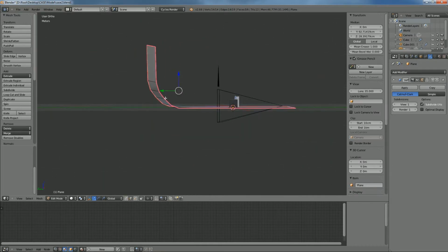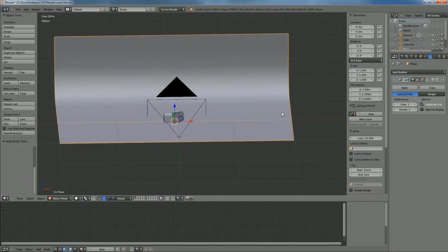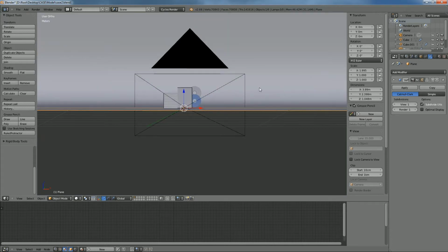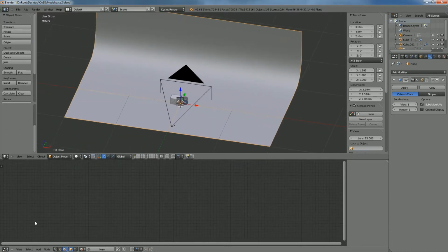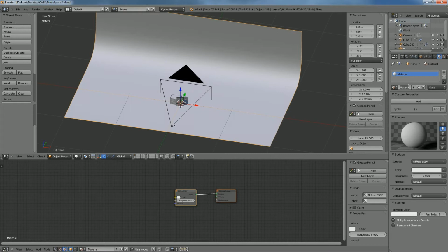And yeah, we can go ahead and maybe tweak some of these just so it's a bit smoother, something like that. Okay, so that'll just give this a nice infinity wall effect, so your scene will just kind of fade off into infinity as an illusion. But then this material, if we go to the node editor and give it a material, we'll call this backdrop.